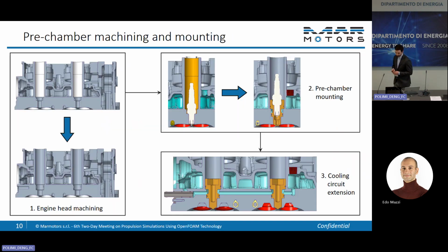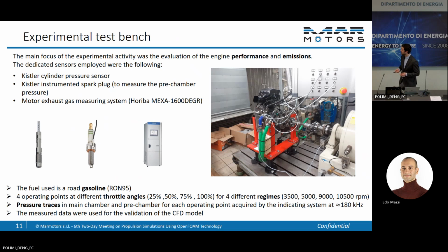So this is briefly what we did to mount this device, this adapter that is our passive prechamber, and we also used an already present channel that we use for purging water out of the engine to cool down the prechamber.